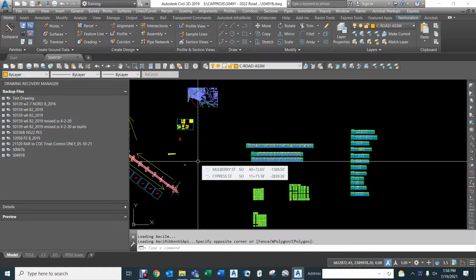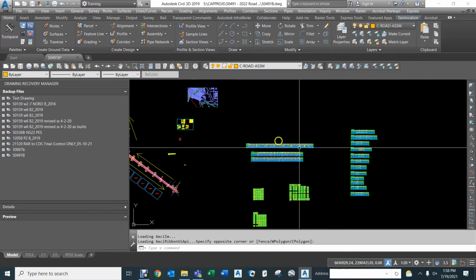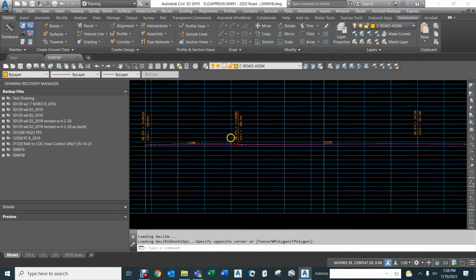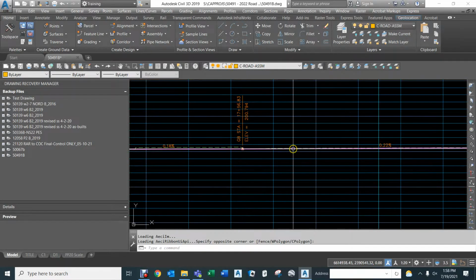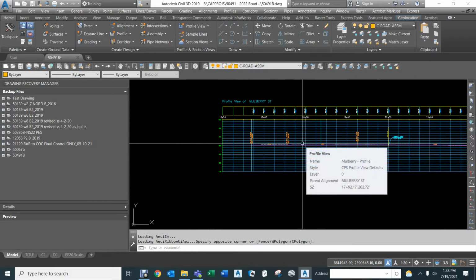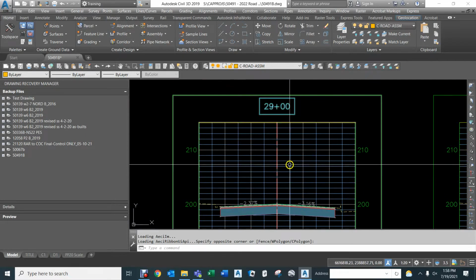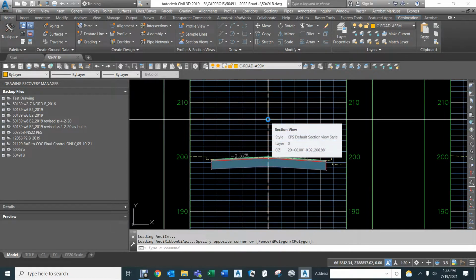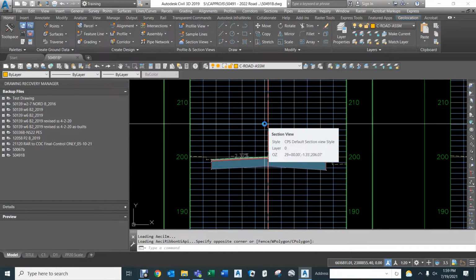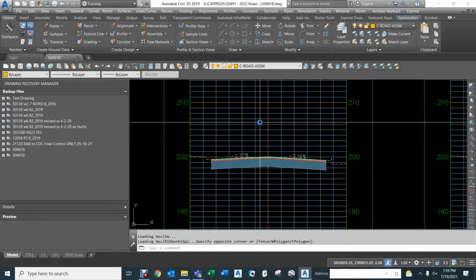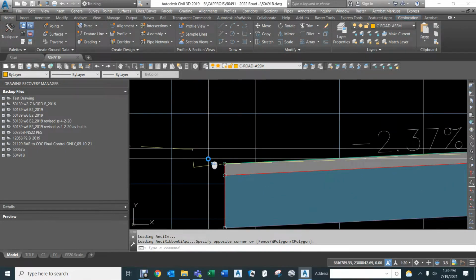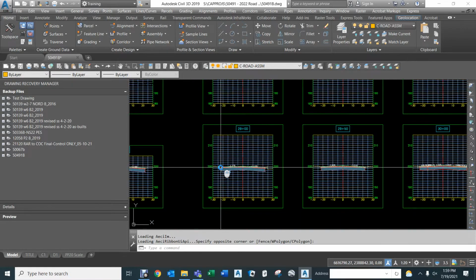Here we have a project. It's going to be a roadway project corridor. And so we have gone through and adjusted the center line to match, for the most part, except for the intersections, what needs to happen to get decent cross slopes throughout, anywhere from about 2 to 3%, trying to keep it above 2 and really probably less than 4 as a cross slope. So most of them are 2 to 3%, and then they've all been transitioned to be attached to the existing lip of gutter.